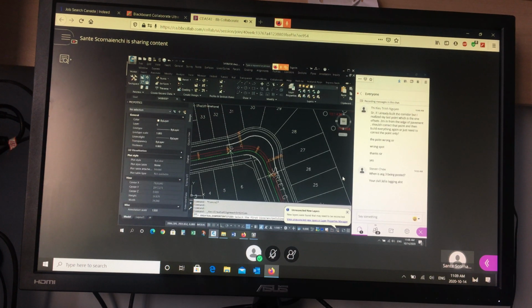I'm going to pick near the beginning. I want the station values to increase parallel and in the same direction as the center line. So if 0 is down here, I want 0 to be at this end, not at this end. So I'm going to choose this front half, the beginning half. When I hit enter, yep, I want that direction. You can see the arrow indicating the direction of increasing chainage. So the direction of chainage for the edge of the road is in the same direction as the center of the road. And then I have to give it a name.